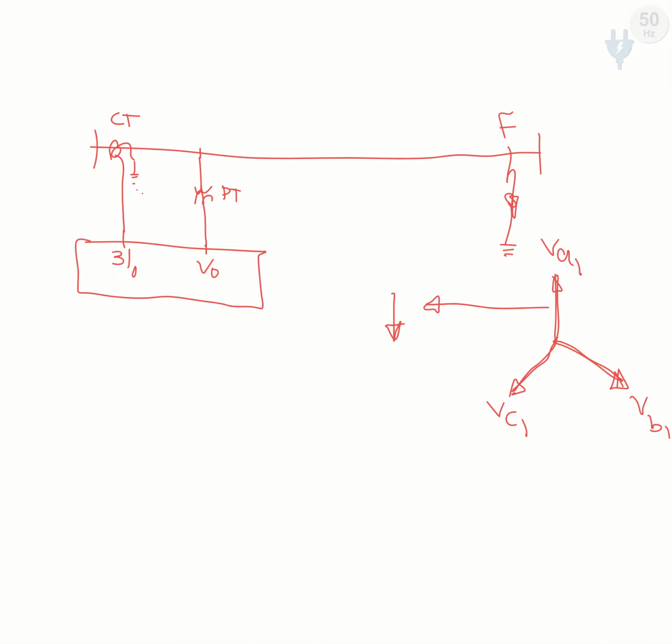almost in the reverse direction of VA1, meaning the positive sequence voltage. So the V0 becomes negative in direction, and in the phasor it becomes almost on the negative side in a purely resistive fault. So we consider our system to be purely resistive, and we assume that V0 becomes opposite in direction. The polarity changes from positive to negative. So in this condition, if we calculate